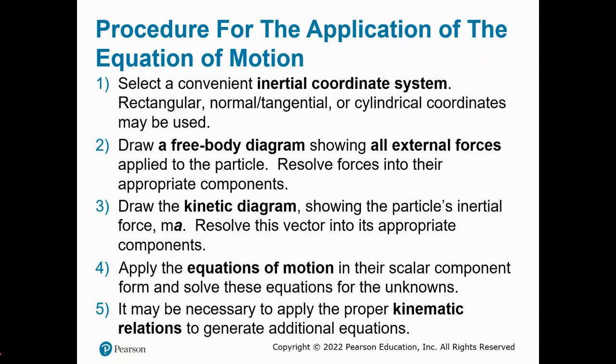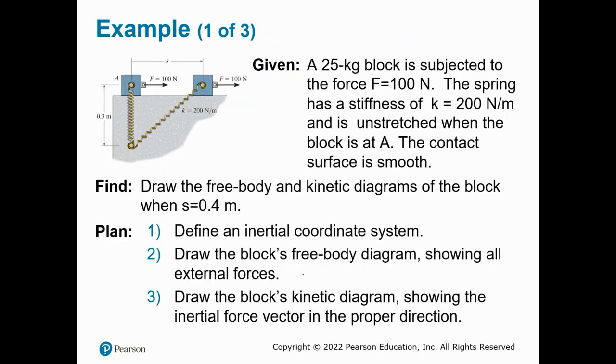And keep in mind that when we say the free body diagram shows all the forces, that will be all your F, and then the kinetic diagram will be your ma, right? F equals ma. And then resolve the vectors into appropriate components. We're going to apply the equations of motion in scalar component form and solve these equations for unknowns. It may be necessary to apply the proper kinematic relations to generate additional equations.